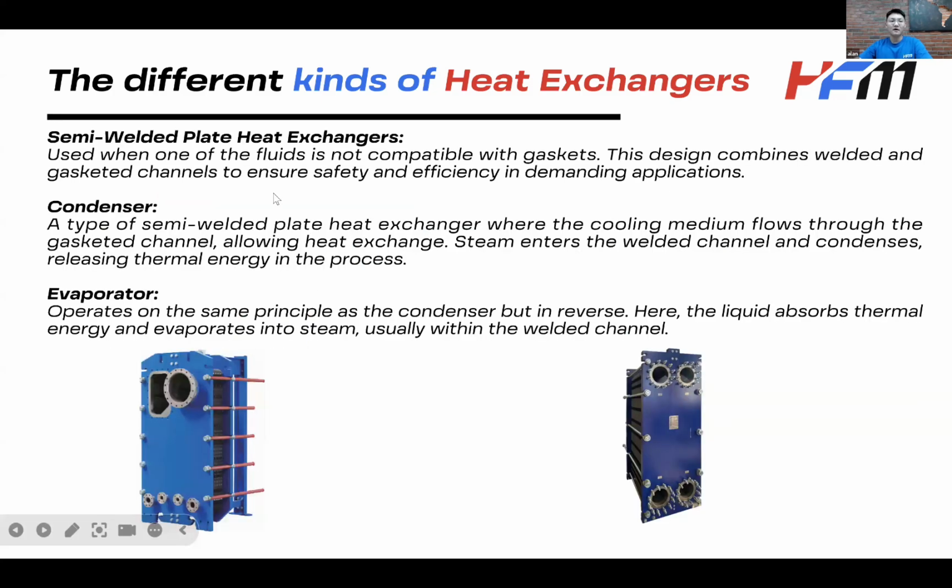Okay, next one we have the semi-welded plate heat exchanger. I think this type of heat exchanger is interesting in terms of the structure because the design combines both welded and gasketed channels. And it will be used when one of the fluids is not compatible with gaskets, for example, ammonia. And this type of PHE is usually used as a condenser and evaporator.